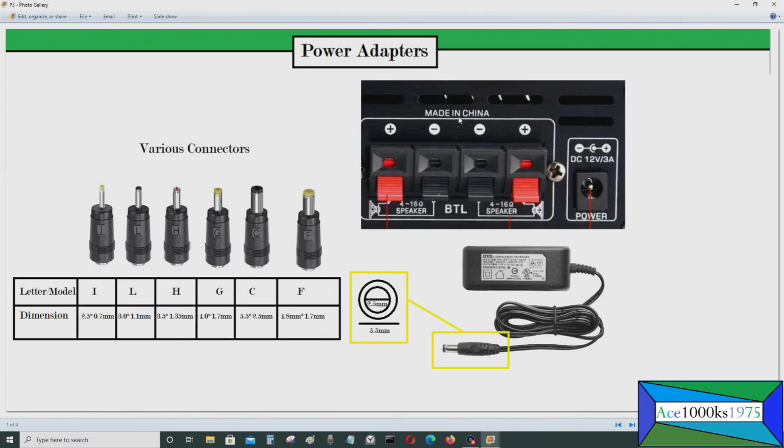Okay, now this part, selecting the right type of connectors for your power supply. For most products that you're plugging your power supplies into, it will have the dimensions of the power connector that you will need, but sometimes it doesn't. So in order to measure it, you'll need a caliper, and you measure the outer shell of this circle.